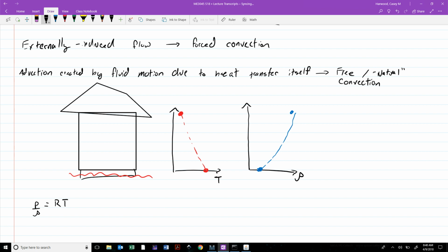In the extreme case, think about what happens to helium if you release helium at floor level. A less dense gas surrounded by a heavier gas, it moves up. This density variation creates a buoyancy force that wants to pull this less dense gas up towards the ceiling, and in return force the denser gas down towards the floor. So you end up with this rising of light air and this downward circulation of heavy air. Okay.